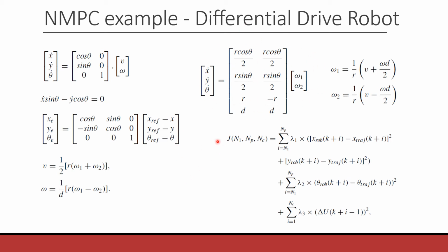Also, equation 4 can be easily manipulated to show the direct relation between the control output to the desired trajectory and the input, the right and the left wheels' angular velocity, as shown in this equation 6.